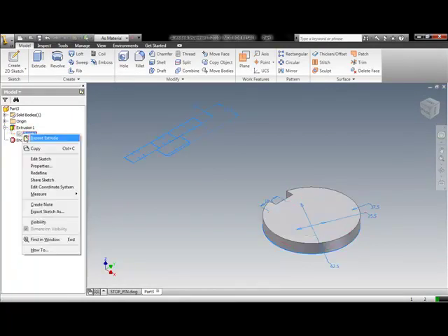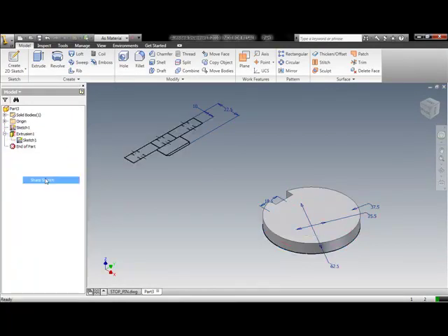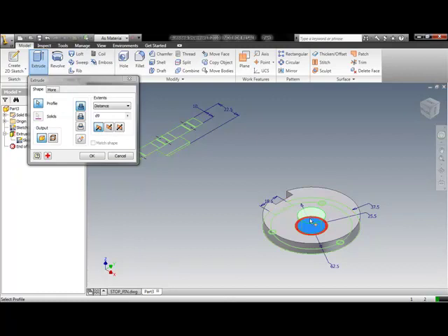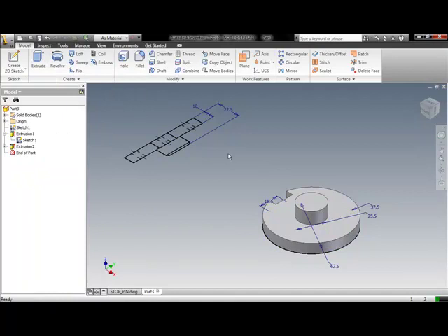Now we want to use that geometry over and over, so we can simply share that DWG file or that sketch inside of Inventor. So any additional extrusions we make, like the center hub of this pin, again we can use that 22.5mm dimension from the side view.